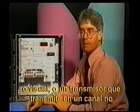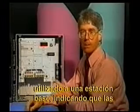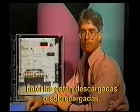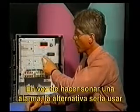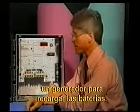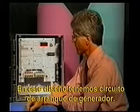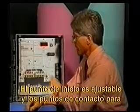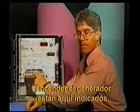Might even operate a transmitter that would transmit on an unused channel to a base station, indicating that either the batteries are undercharged or overcharged. Instead of simply sounding an alarm, we may want to actually operate a generator set to charge our batteries back up. In this particular design, we have generator start circuitry. The starting point is adjustable, and the contact points for starting the generator are indicated here.